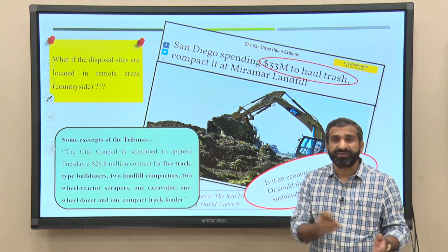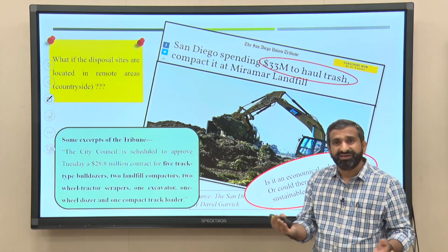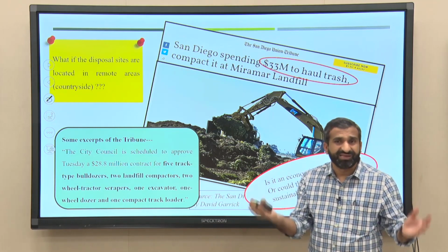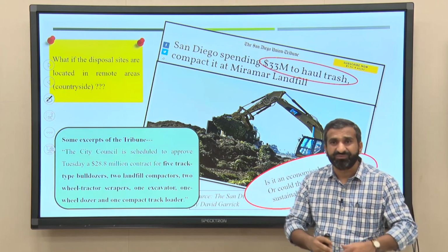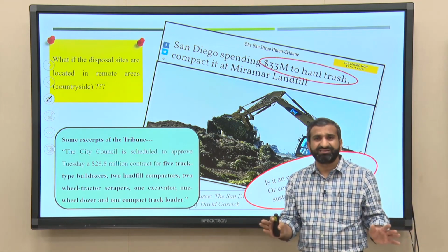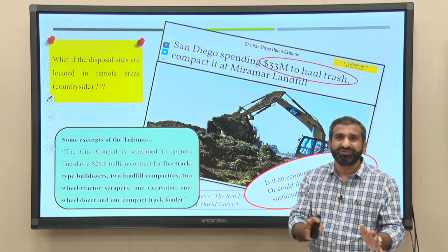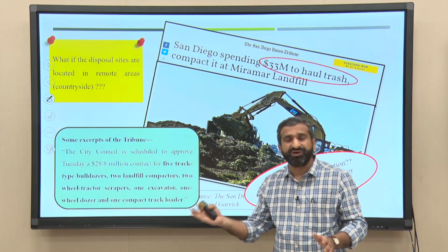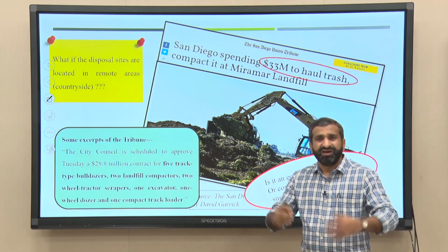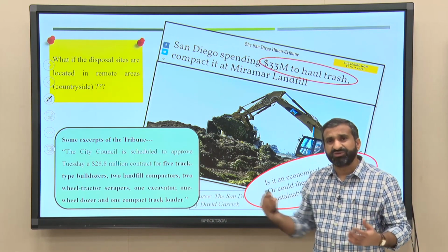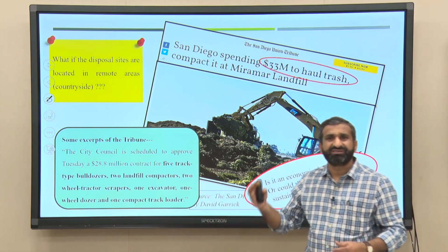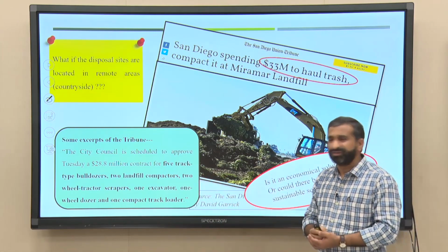And if you are specially planning for a hauled container system, having the waste of only 2 tons, 3 tons in a trip means the collection cost will be very high, and because of that the haul collection system is also difficult to accept. In that case, we have to go for a stationary container system, and you know that there are a lot of issues about the stationary container system. You can't collect a large amount of waste from the hauled container system.